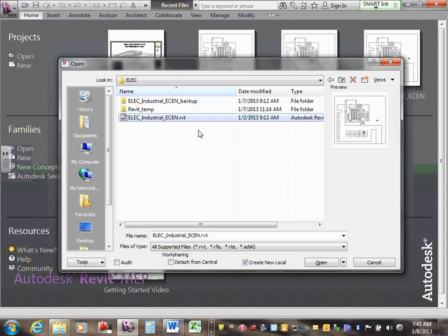Brian, Jamie, you're good? Okay, like I said yesterday, when you guys open the central file to work smoothly like we have done in the commercial project, please always do it this way. Open Revit first and go open the central file. That's the process that we do. It seems to work perfect for us, right? Cool? Yes, no? It doesn't automatically sync when we first start off. We need to sync after you start it. When you upload it, you have to sync. But we open it first and we work on it and then we do the syncing.